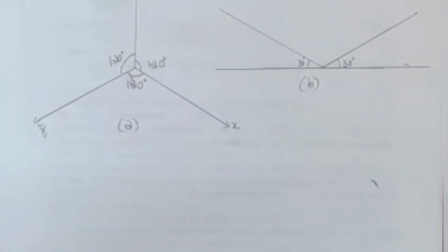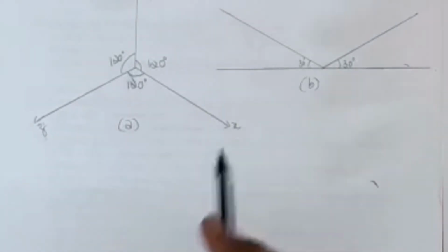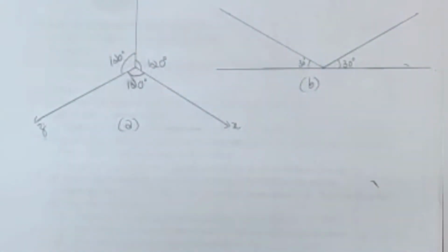An isometric view of an object can be obtained by choosing the viewing direction such that the angles between the projections of the x, y and z axis are 120 degrees, and an isometric uses a plane grid at 30 degrees from the horizontal line in both directions. The isometric graph can be used to make these kinds of drawings. This is called as ISO sheet.